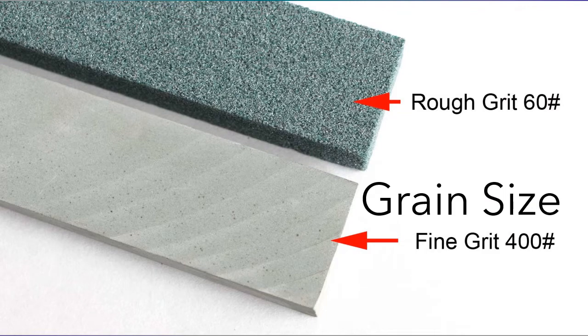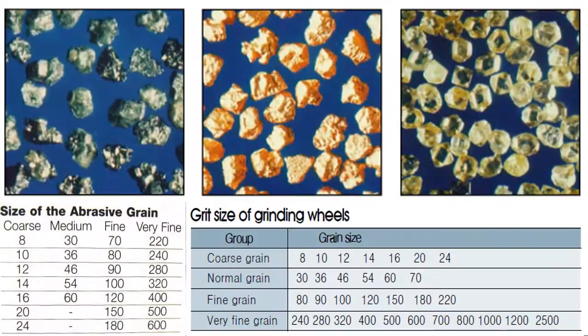The grain size of the abrasive particle is important in determining the surface finish and the material removal rate. The smaller grit sizes produce a better surface finish. Larger grit sizes permit a larger material removal rate. Harder work materials require smaller grain sizes to cut effectively, and softer materials require larger grit sizes.